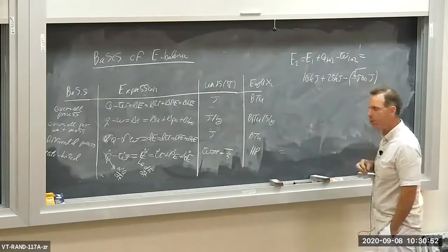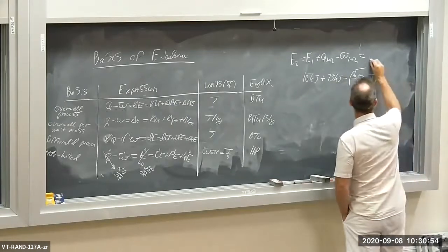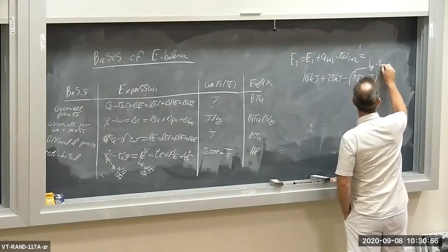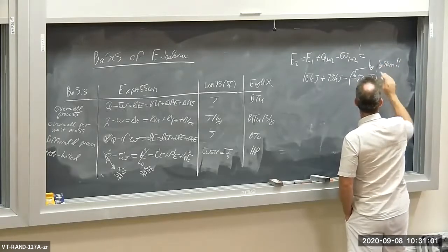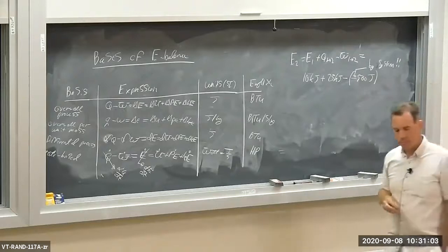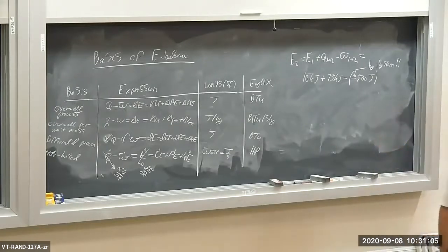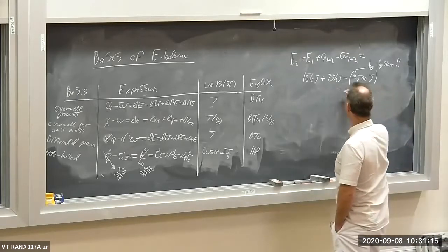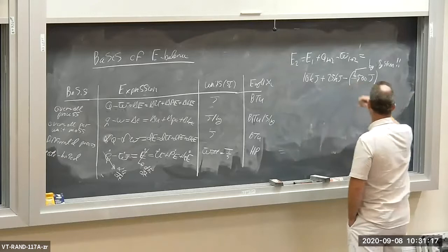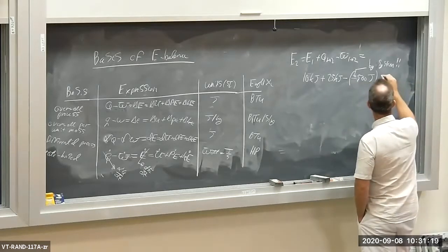Because this needs to be work done by the system. That's why we have the negative sign, so we take work on the system and convert it into work by the system. All right? Now, one little thing here, the units need to be the same for all the terms. This is in kilojoules, kilojoules, joules. Ooh, we need to convert this.